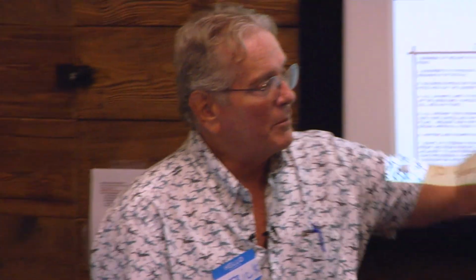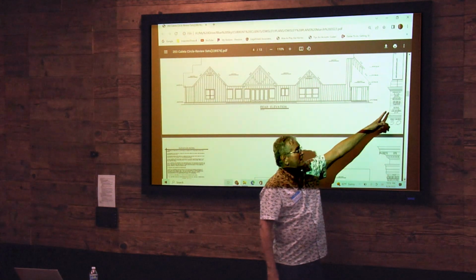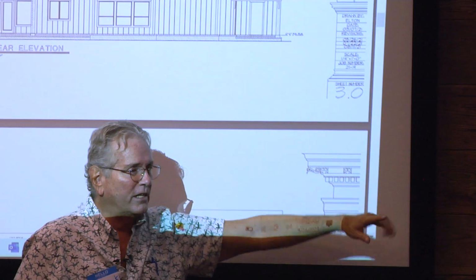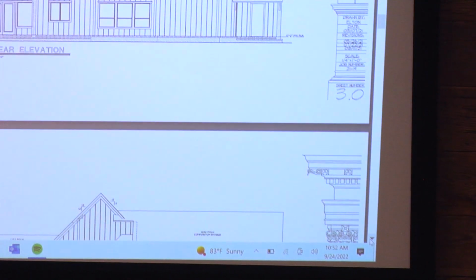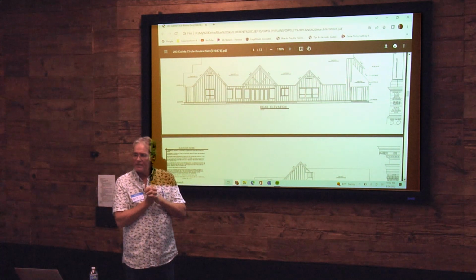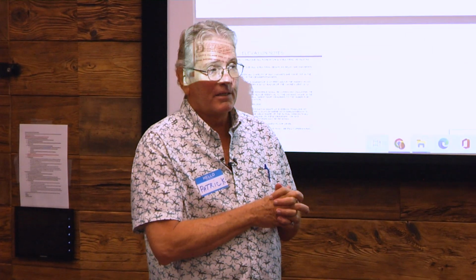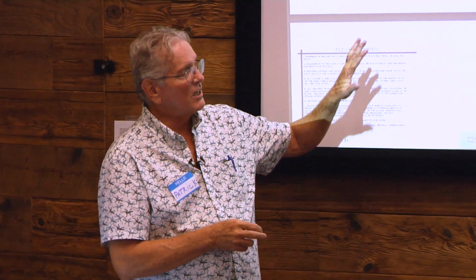Then the title block down at the bottom, right here. Again, important information here. It's telling you the scale of the plan. If it's not 1/4 inch equals 1 foot, they've got it on some scale that's not typical. 1/4 inch to a foot is a typical scale. Is that what the architect used, a quarter per foot? But that is the typical scale. If you see something different, you need to ask the designer why. That goes into a whole different conversation of when you make copies of those plans. You need to know what kind of scale you want to show up on those plans when they're copied.